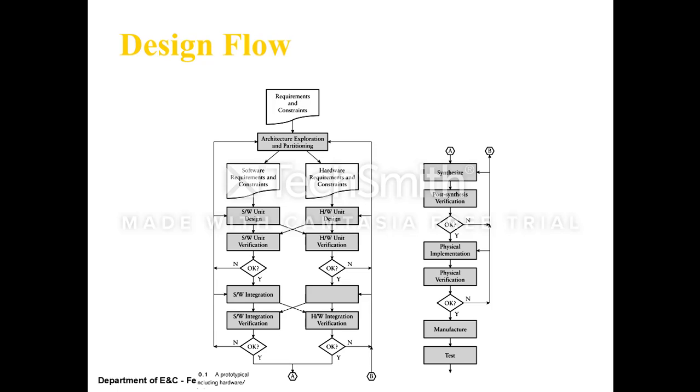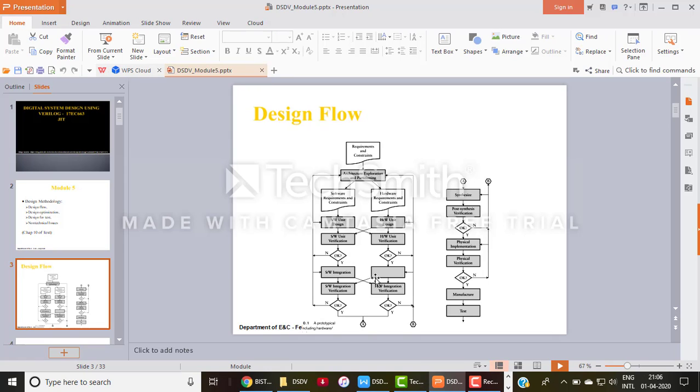Once the software integration and hardware integration are completed, we proceed with the next stage: software integration verification and hardware integration verification. If both are fine, proceed for the synthesis, then post synthesis verification. If that's fine, proceed for the physical implementation,